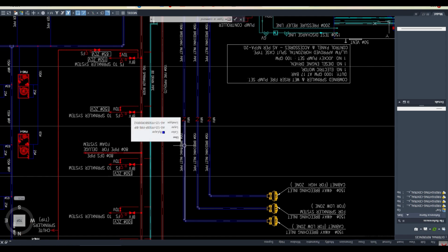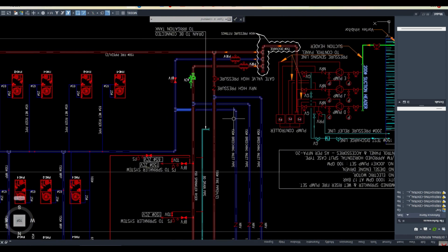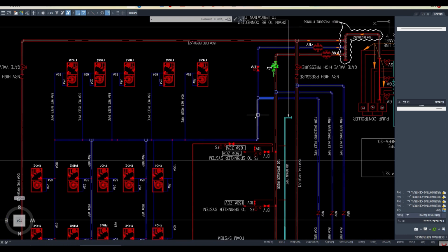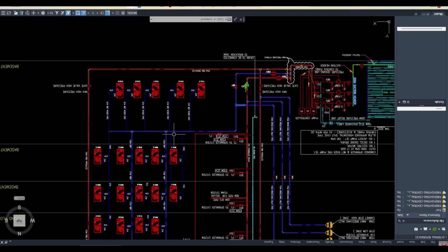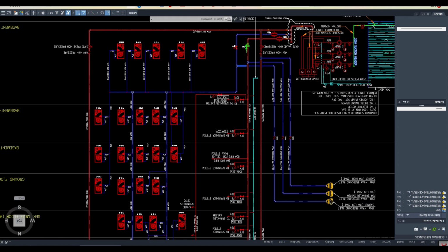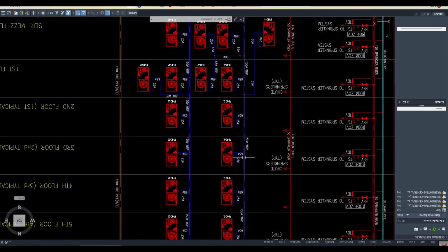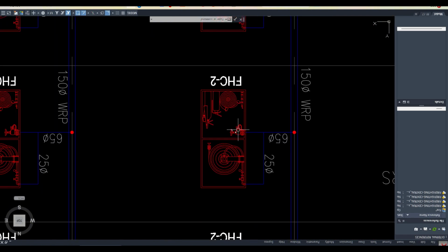They have the ready-made system, everything loaded with the water. So they will just connect this pipe, and from here the water can come and go in this system, and then another fireman who is operating the truck will connect their hose to this fire breaching inlet, and from here the water is going to the floor, and another fireman will go to that particular floor, and then they can operate this hose reel system.